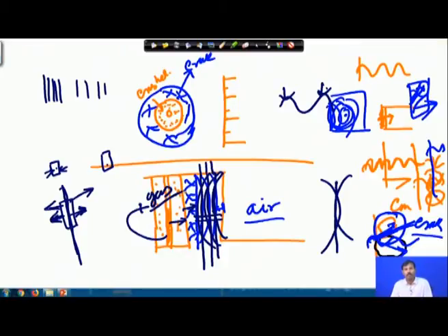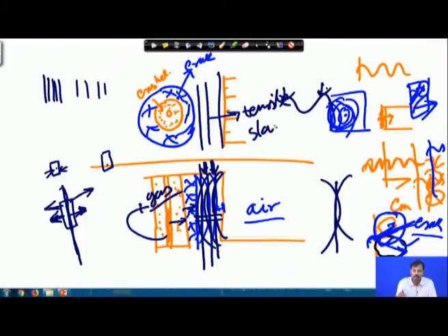Because there is a time gap between the shock energy release and the gas energy release, what we want is that before the release of the gas energy, or before the gas formed reaches the cracked position, our tensile failure, which is called tensile slabbing, must be completed ahead of the gas reaching this position.